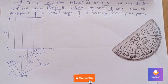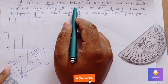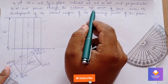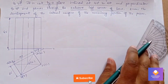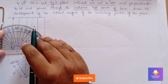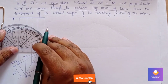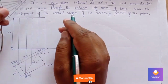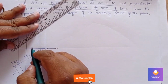Okay, so now we can see there is a cut plane, there is a sectional plane cutting at an angle of 40 degree to HP, and it is perpendicular to VP, passing through the extreme left corner of the base. You can see extreme left corner we need to consider here. So this is the extreme left corner. Keep at this exact point, and mark for angle 40 degree. Draw a line, cut plane here, passing through this angle point.